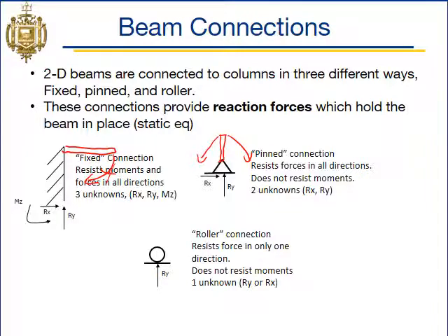And a good example of a pinned connection is your door hinge, right? You can't rip the door off the wall, so the hinge is resisting x and y forces, but the hinge doesn't resist moment, which allows you to open and close the door.